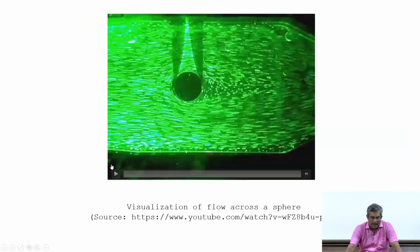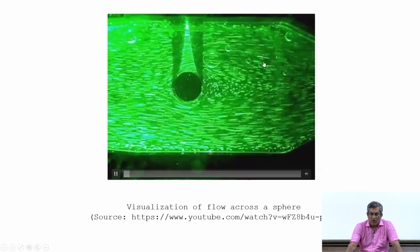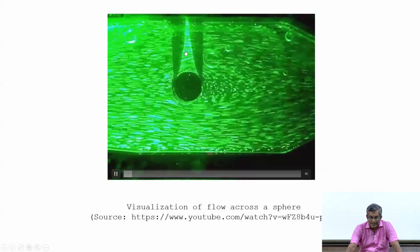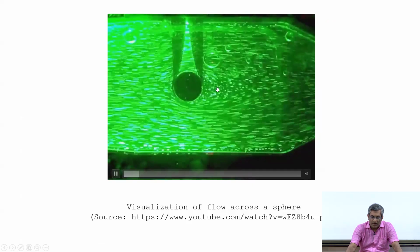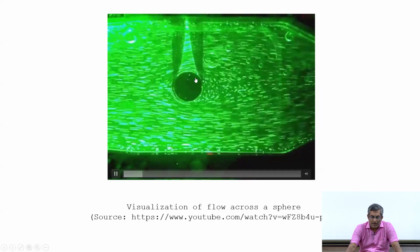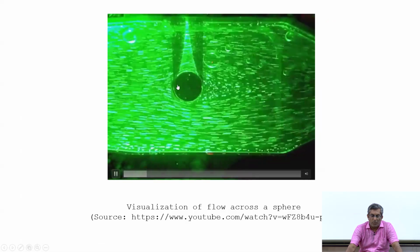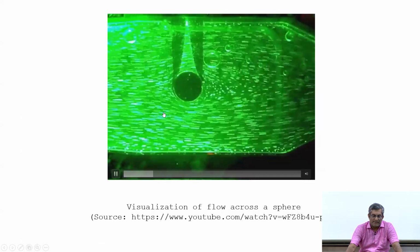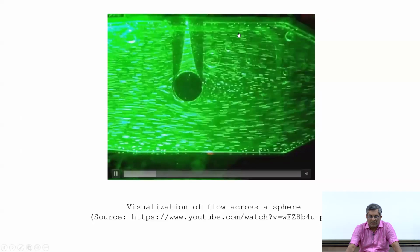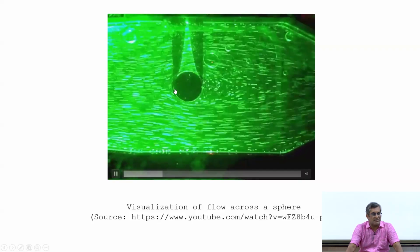Then, this is an example that I always show to understand the concept behind PIV, though this is not strictly a PIV image. Here you have a video of flow behind a circular cylinder. The flow is seeded with small particles, and this is illuminated with a laser sheet.